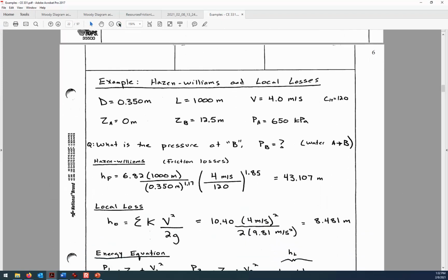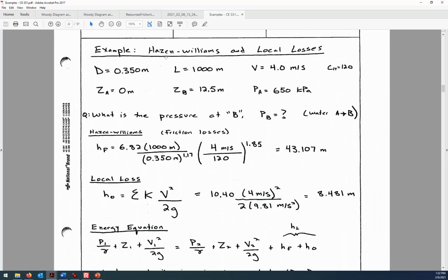Okay, so I got a good question just a moment ago about that length. Is that talking about the pipe length, or is that a plan view length where we need to separately keep track of the pipe length? Even for a relatively steep pipe angle of maybe 10% or even larger, the distance between the inclined length and the horizontal component of the length are close enough that we're not going to differentiate between the two. So we'll use that as the L that goes into the Hazen Williams equation.